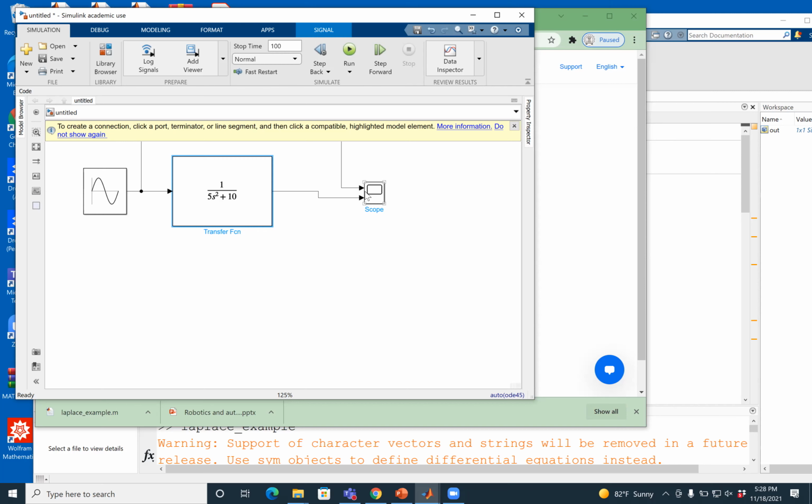If the input frequency matches the natural frequency of the system, the response becomes infinite, because that is what is called resonance. At resonance, there is a free transfer of energy from the external input to the system. So if there is no damping, if external damping is 0, the system would start vibrating violently.